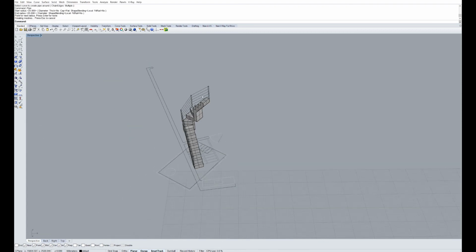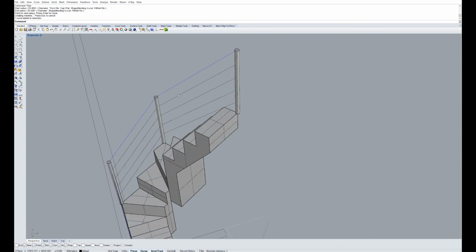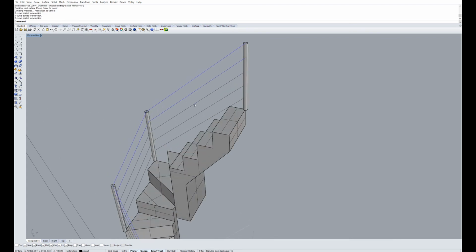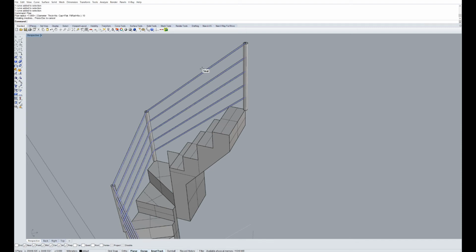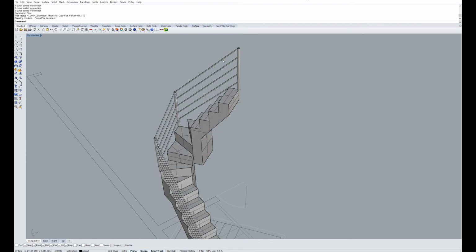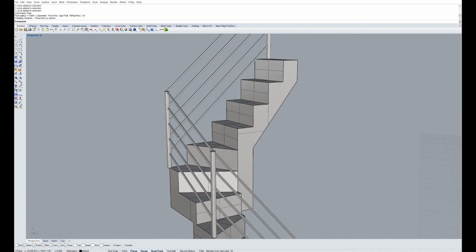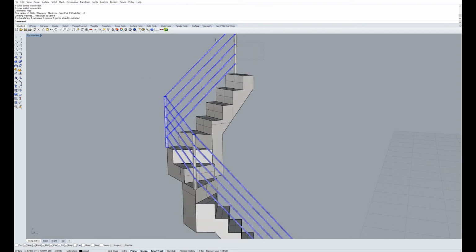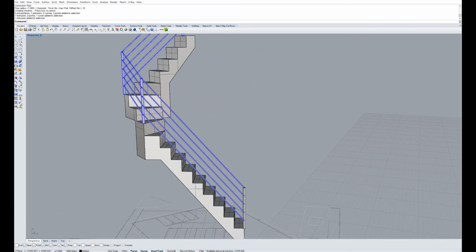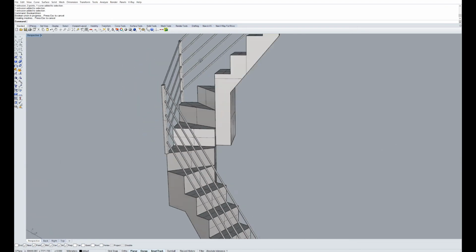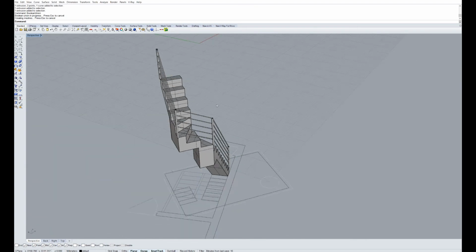And the wonderful thing about it is that you can actually select polycurves as well. I'm just going to create a slightly thinner radius through them, and you can begin constructing your railing this way as well. Just going to Boolean union these together. So as you can see, now these things have become rail.